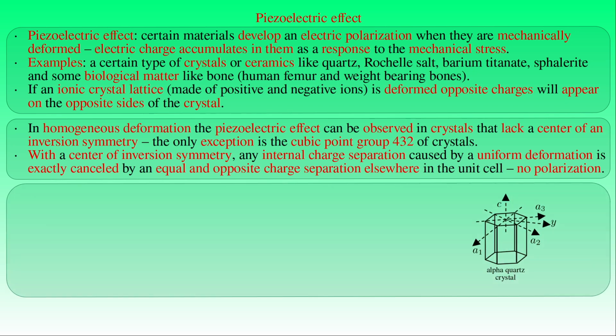We already saw in the discussion on anisotropic dielectrics that alpha quartz crystals have one threefold axis in the z direction called c-axis or optical axis, and three equivalent twofold symmetry axes called a-axes or electrical axes, which are perpendicular to the c-axis. Between the three a-axes, other three symmetry axes called y-axes or mechanical axes of the crystal can also be defined. Here we depict one of the y-axes between the axes A2 and A3. In preparing the quartz crystal for the experiment, a thin plate is typically cut so that its faces are perpendicular to one of the crystallographic axes.